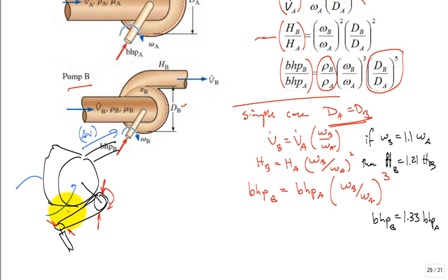You know, change it from a 20-inch or 10-inch to an 8-inch or some other. And the same electric motor is going to be driving it, but now the pulleys are going to make it go faster. And you'll have to adjust the belt a little bit, but you can handle it. And that's great, and now he's boosted the volumetric flow rate. The new volumetric flow rate is 10% greater than the old volumetric flow rate. Everything's running okay for a day or two, or a week, or a month. And then what happens is this thing gets toasty hot and burns out. What didn't he consider?